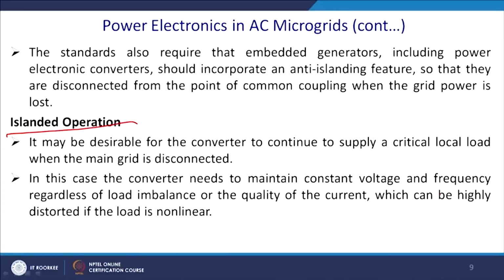In this case, the converter needs to maintain a constant voltage and frequency regardless of the load imbalance or the quality of the current, which can be highly distorted if the load is non-linear.